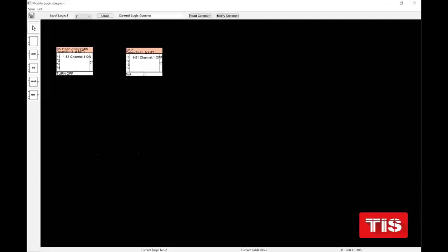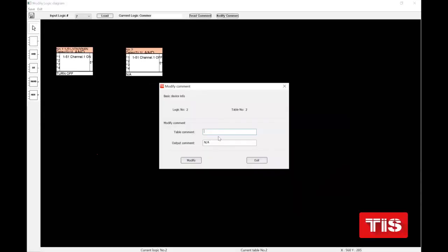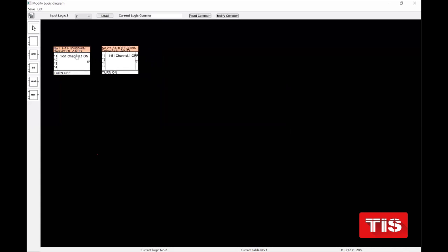That's it. And put a comment: 151, channel number 1 off 30 min, then turn it on. With these two logics, channel number 1 is 30 minutes on, 30 minutes off, 30 minutes on, 30 minutes off. Next question.